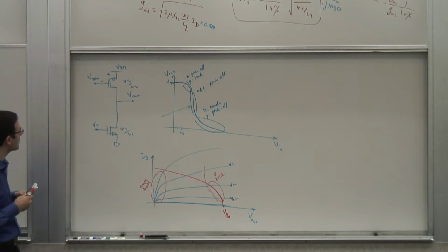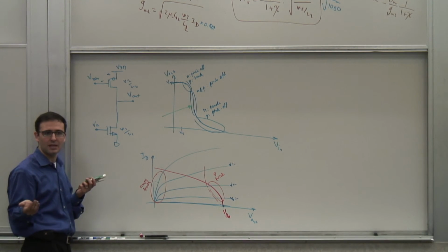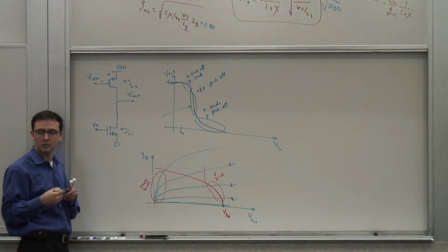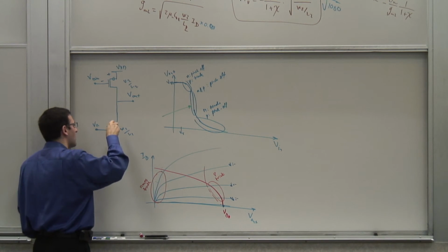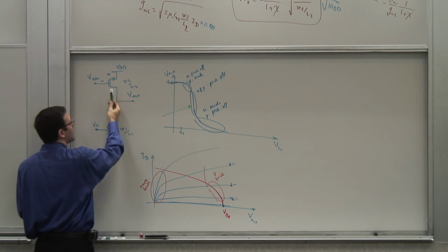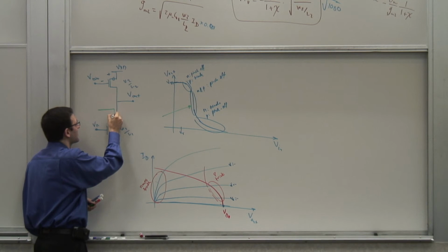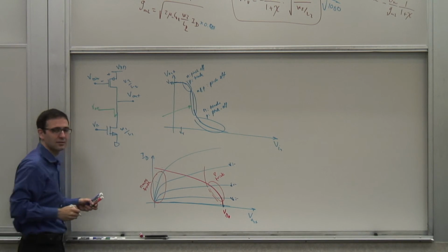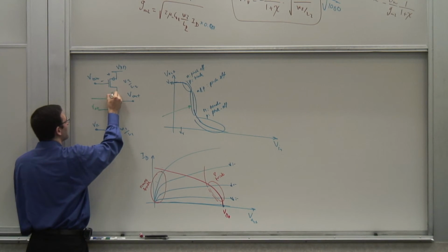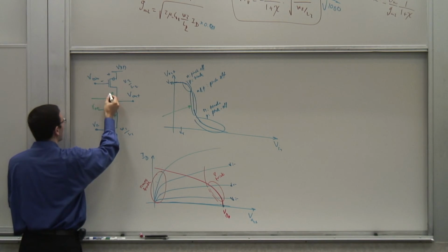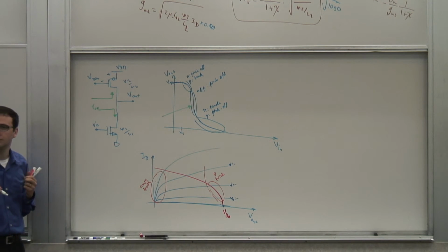So from a small signal perspective, if I were to analyze this, again, I could do everything from scratch, or I could realize that my gain was Gm times RO of this guy times whatever RD was. Looking down, I still see RO of this guy, RON. Now, if I determine the impedance looking up, like I did before, I can just replace RD in that equation with that and be done with it.